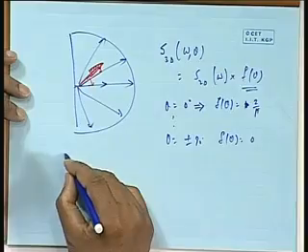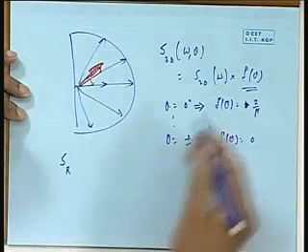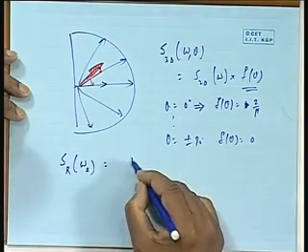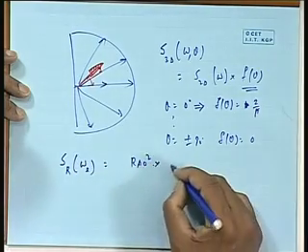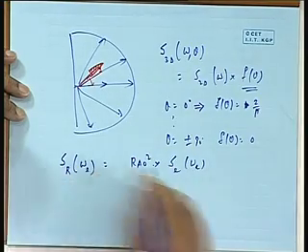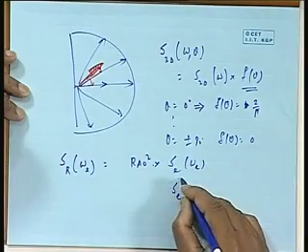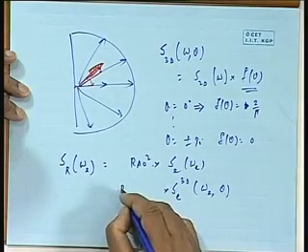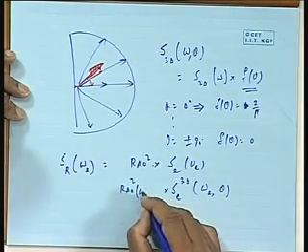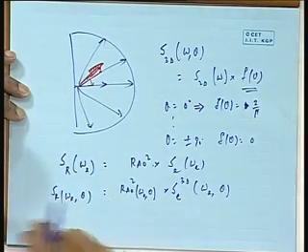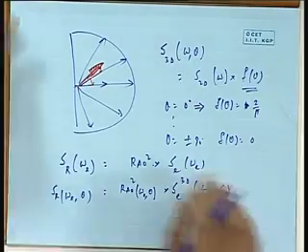angle also. See, if you look at the principle, now the response spectrum, this is response. Let us say I have made these changes to omega e, etc. The response spectrum in omega e is RAO square into S E of omega e. This is my formula. But now my SE is 3D, which has omega e and theta in a 3D case. So obviously I have to have RAO square, which will be a function of omega e and theta, and this is going to be my SR of omega e and theta.